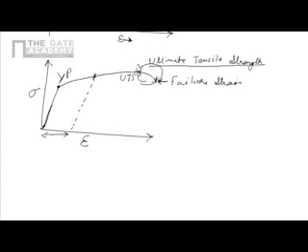For most of our study in this subject, we will not be going beyond the yield point. We will be working mostly in the elastic zone only, which means that if we remove the force, we retract the curve exactly, and as we take the force to zero, all the strain is recovered, which means the strain goes back to zero. Please remember the curve and the various points in this curve.